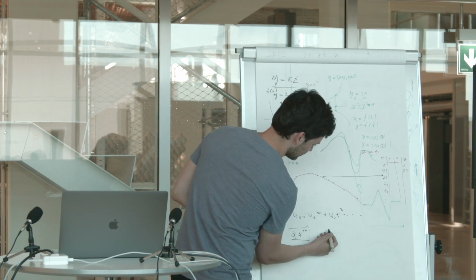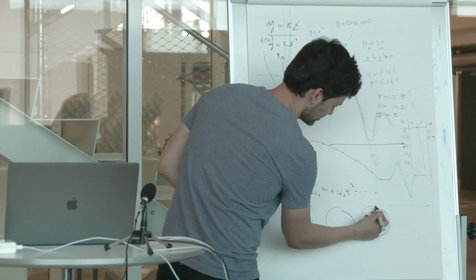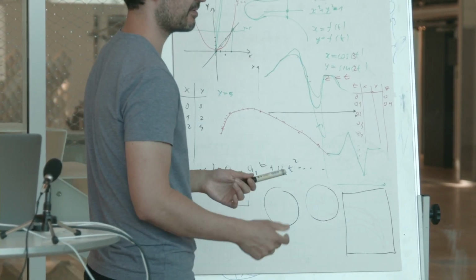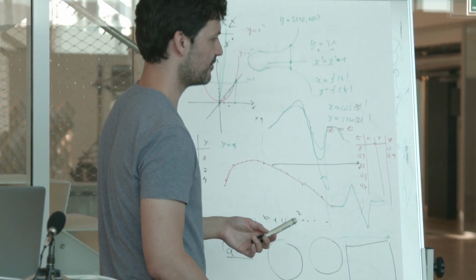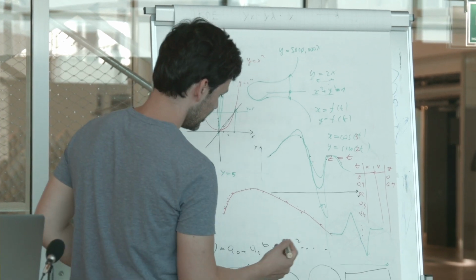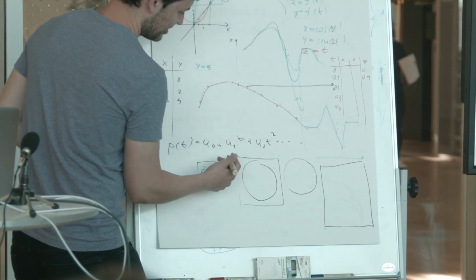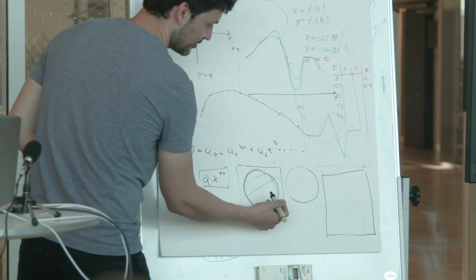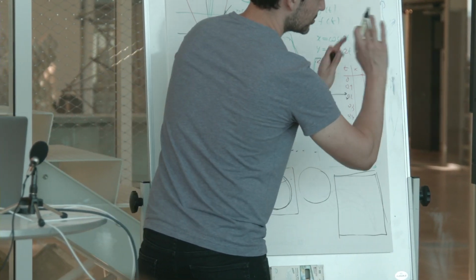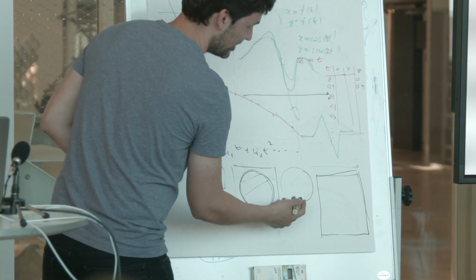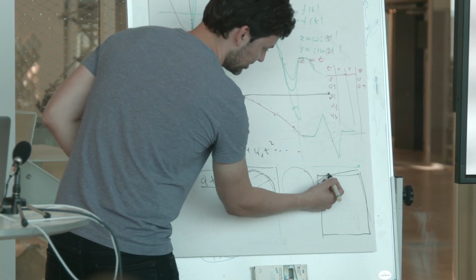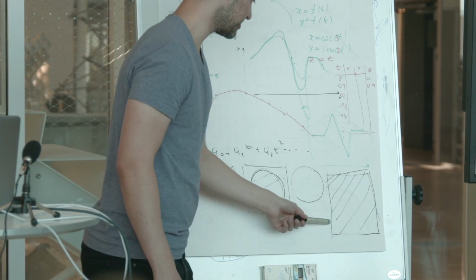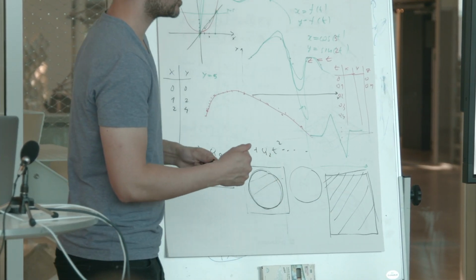So as you know, a cylinder has two circles, and then it has this part which goes around. But to define it parametrically means to define it with a formula so that you can infer each of the points. So somehow you need to take a plane which is unbounded, and define an equation of a circle on it, and define that these elements are in and these are out. Also, this part which goes around the cylinder is a kind of unlimited plane, but within this so-called parameter space, you need to define what are the valid inputs. So what are the parts which are inside? These are defined by these shapes here. Here the shape of a circle and here the shape of a rectangle.